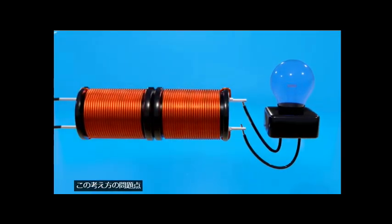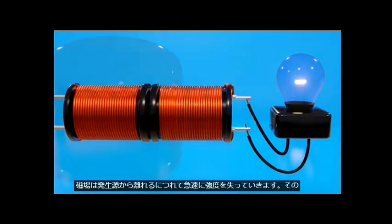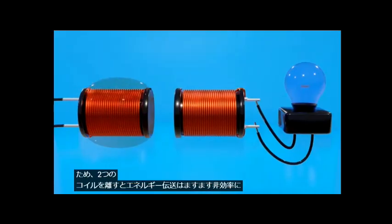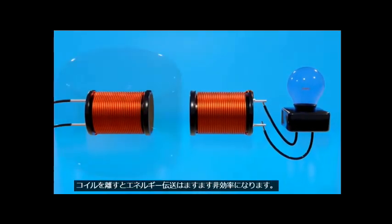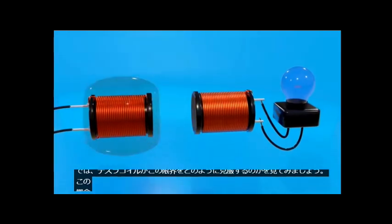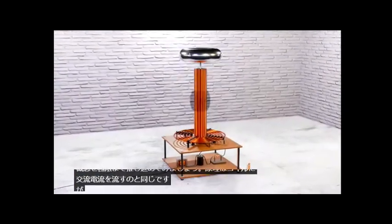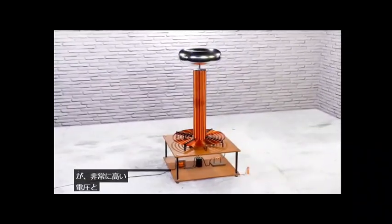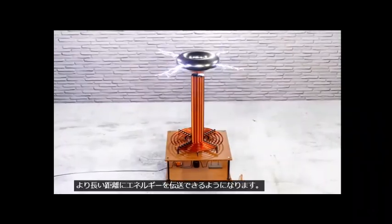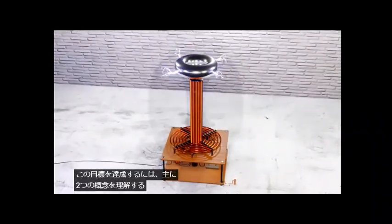The problem with this idea is that magnetic fields lose their strength quickly as we move away from the source, and therefore, when separating the two coils the energy transmission becomes more and more inefficient. Now let's see how the Tesla coil overcomes this limitation, taking this concept to the extreme. The logic is the same: to make an alternating current go through a coil, but with extremely high voltage and a specific frequency to be able to transmit energy over greater distances. To achieve this goal there are mainly two concepts that we must understand.